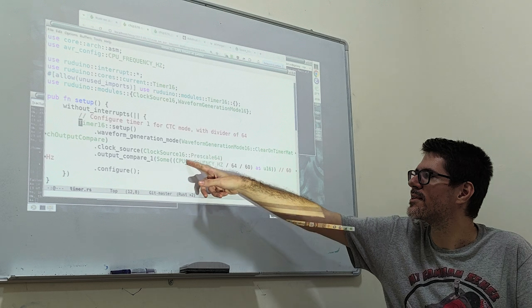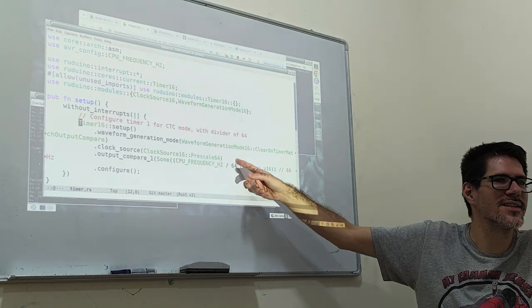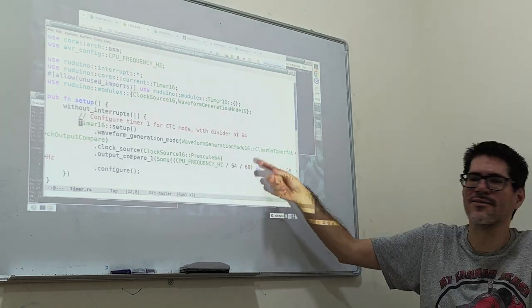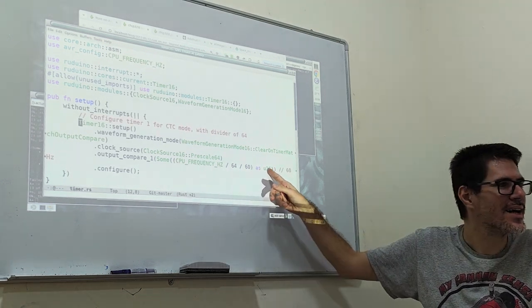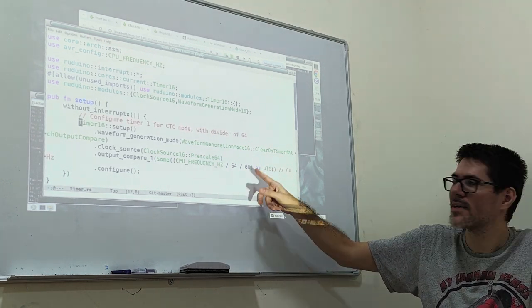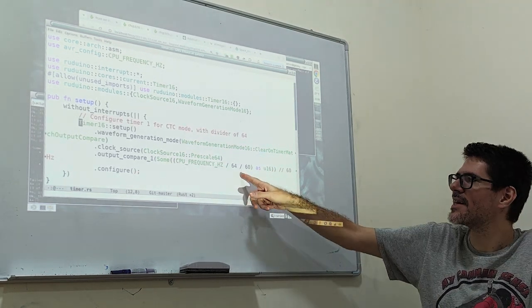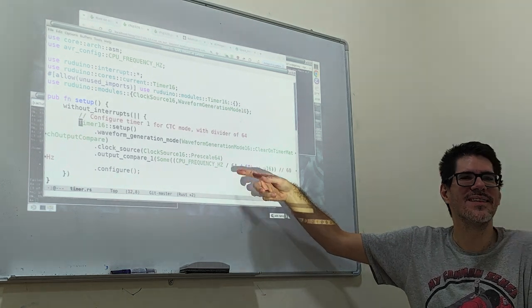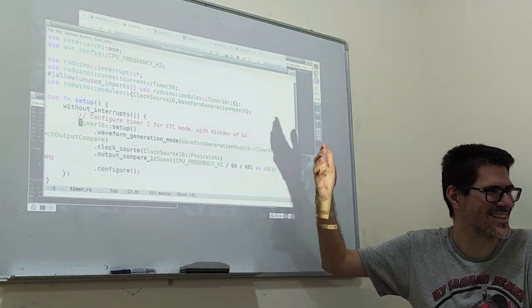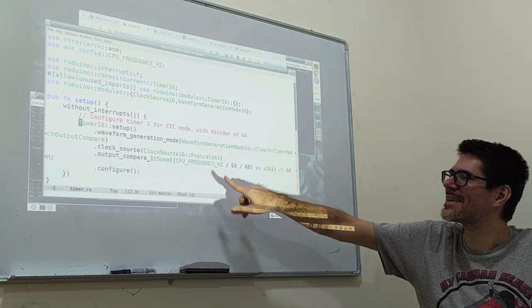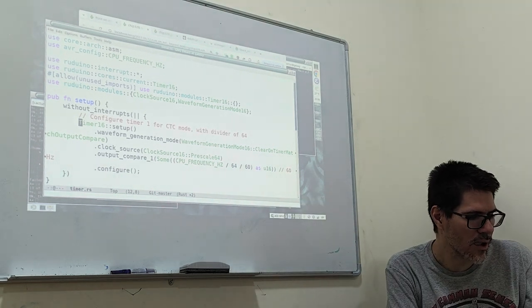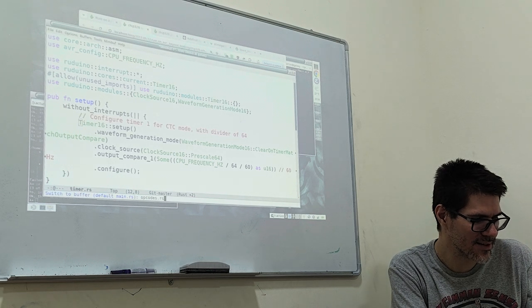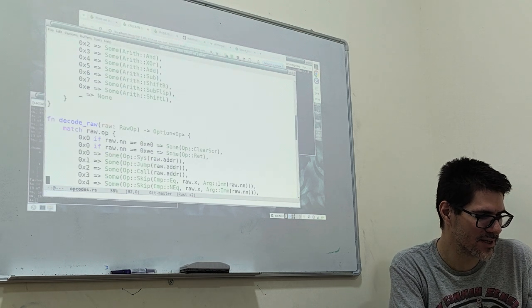That will give, if you were counting up this much, you get a timer every second, but if you divide it by 60 more, and this is of course a compile time calculation, because it's a constant. This is super nice because these chips don't have division instructions, right? But this doesn't matter because this is all happening at compile time. And that's basically it.